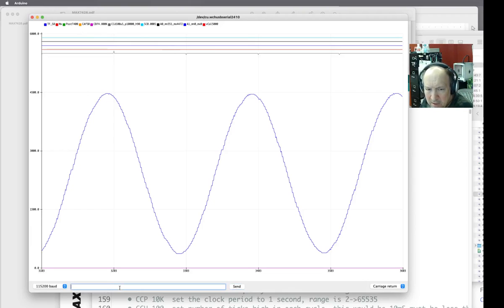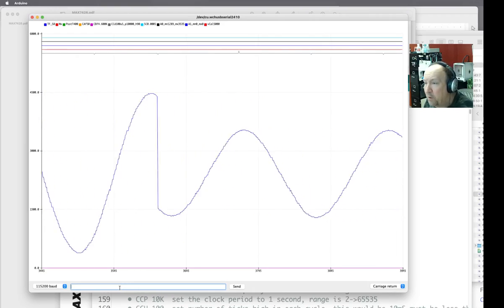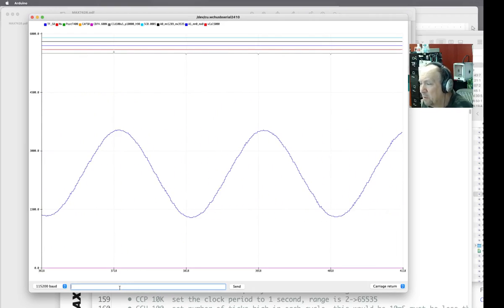If I change clock B frequency to just a little bit less, 4.6 uppercase K, remember it's K, you can see by just reducing the frequency a little bit, our amplitude goes down a lot. So we can actually control our amplitude even with this a little bit.